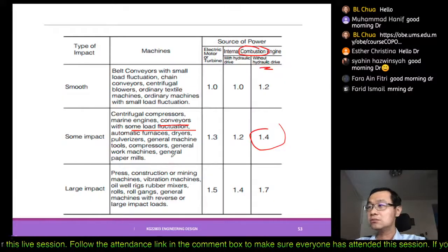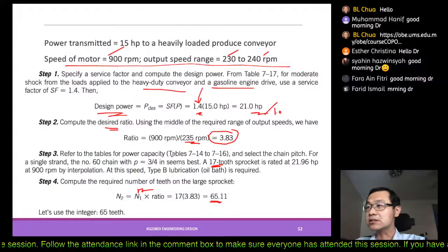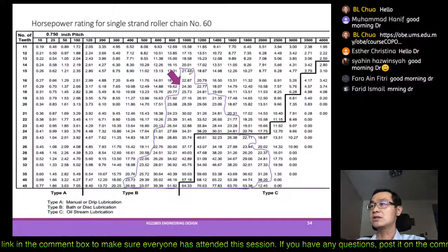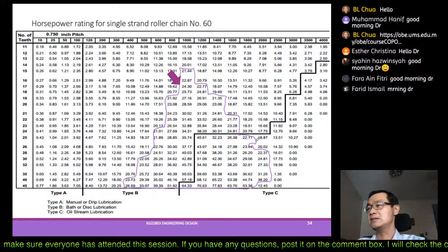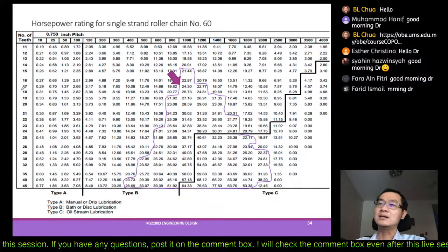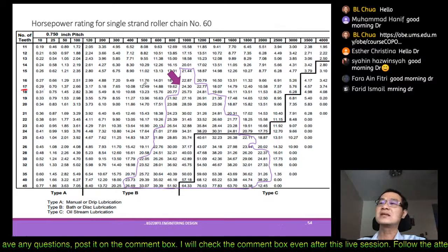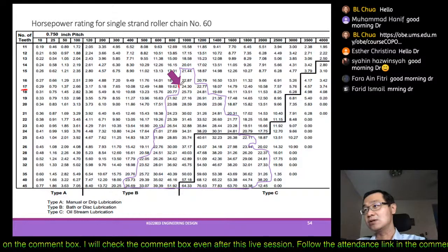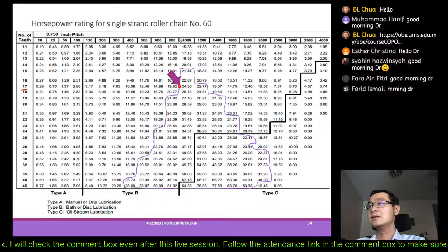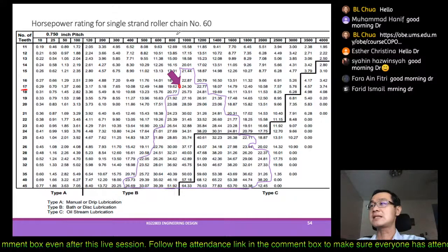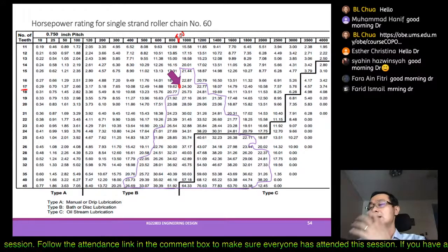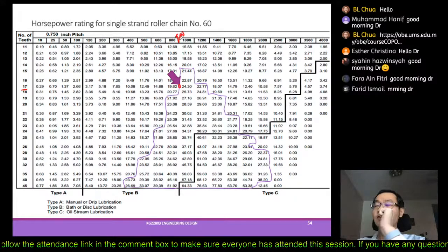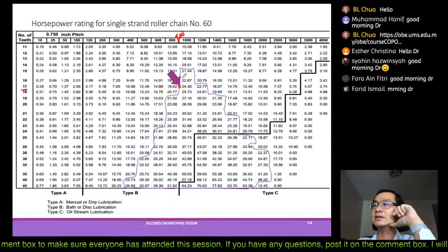Also this is 21 horsepower, so you can see that this is the range that you can have, right? But we start with the lowest, 17, then it will start at this number. So again, since this is 900 in the design, and you don't have 900 in the spec, in the data table, what we do, we interpolate these two values.